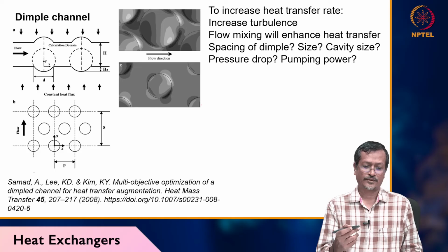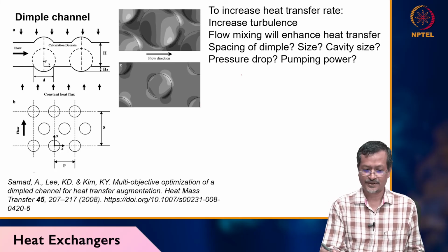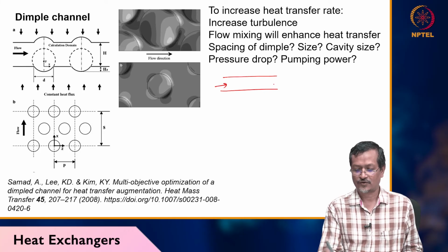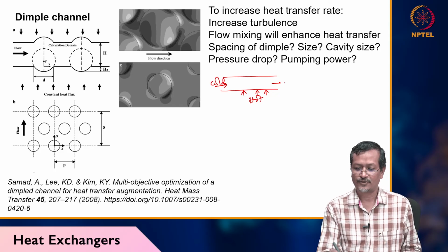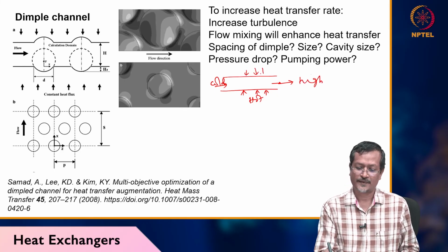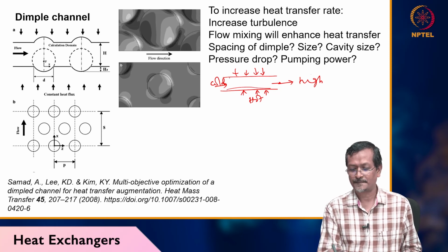And when you are trying to create a compact heat exchanger, I was working during my PhD on a dimple channel heat exchanger. What is this dimple channel? Say I have one flow channel, and the hot fluid heats up the pipe, and the cold fluid temperature is increased to high, okay. Now if you have only a simple channel, then the fluid will create one boundary layer, okay, and the central fluid will be going like this.